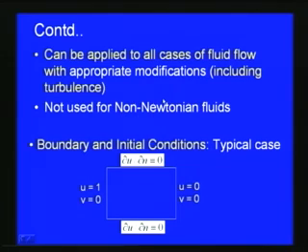Generally, when we use the Navier-Stokes equations, our assumption is that these equations are applicable for Newtonian fluids. For non-Newtonian fluids we cannot utilize these Navier-Stokes equations. So, with the given equations for the given problem we have to supplement the initial and boundary conditions. Here, for a 2D problem, the initial conditions can be either velocity or pressure distribution known throughout the domain, and the boundary conditions we can supply generally in terms of velocities or, depending upon the problem, pressure or other parameters.